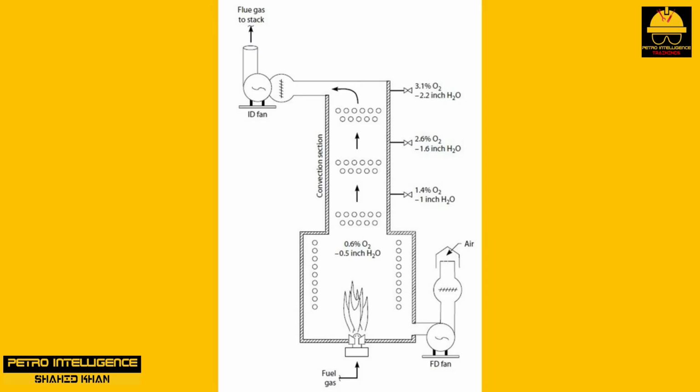The convective section flue gases then cool and shrink, re-establishing a negative pressure as before, and, as before, air leaks into the convective section and the hot, unburned hydrocarbons from the firebox mix with that tramp air and reignite in the convective section. This cycle of events will continue, except each time the ambient hydrocarbons ignite in the convective section and the pressure changes from negative to positive, the leaks will increase in size as the boiler fabric is shaken.